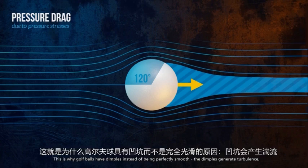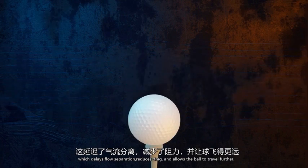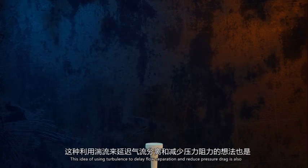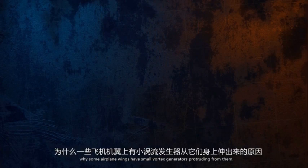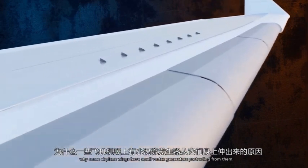This is why golf balls have dimples instead of being perfectly smooth. The dimples generate turbulence, which delays flow separation, reduces drag, and allows the ball to travel further. This idea of using turbulence to delay flow separation and reduce pressure drag is also why some airplane wings have small vortex generators protruding from them.